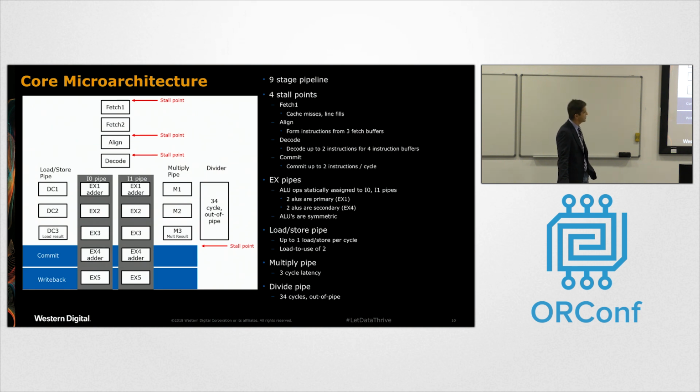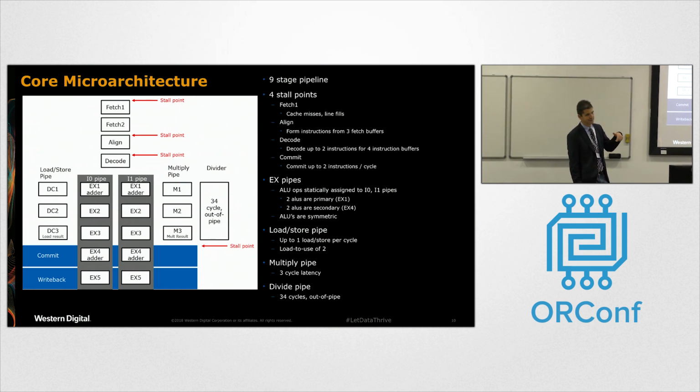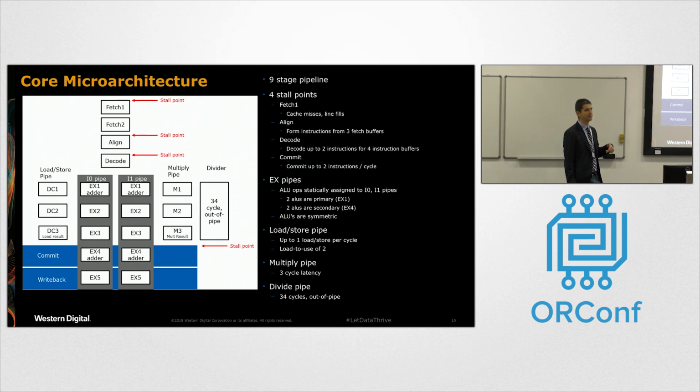The interesting feature, depending on what you have seen before about this design, is that you can do your arithmetic operation either at EX1 or at a later stage in the commit. Meaning if you miss something, like you have a load that will give you a result with two cycle latency, you can actually do it later in the pipe and improve the throughput.